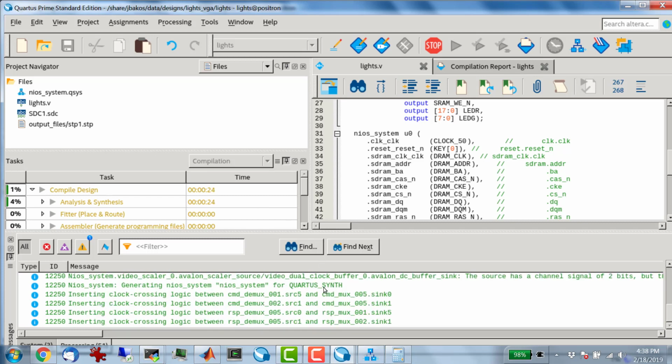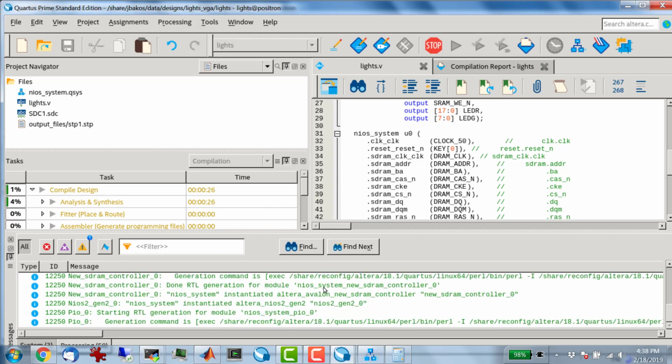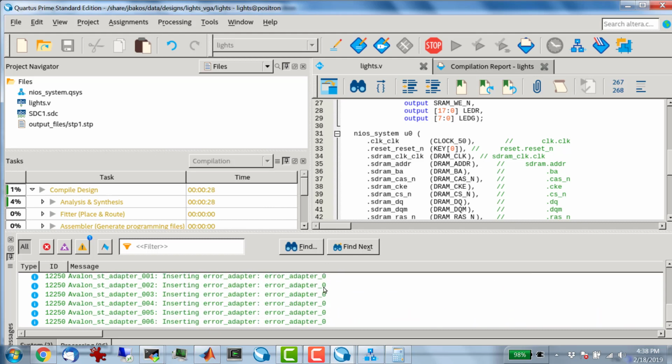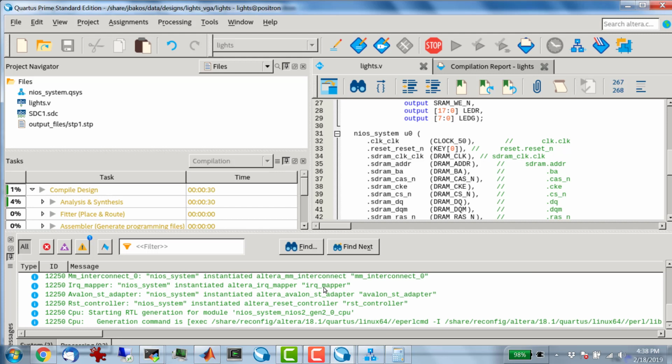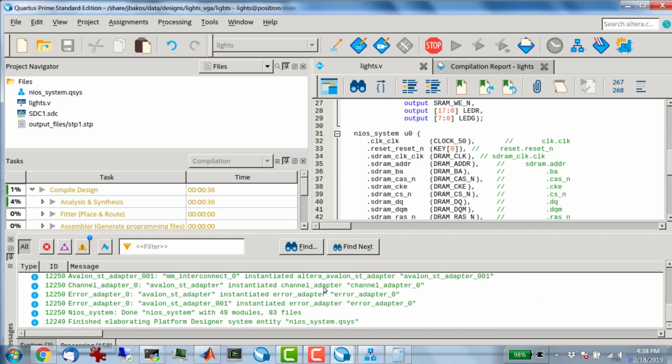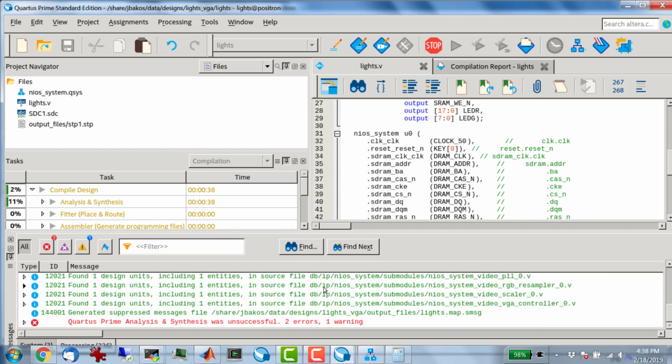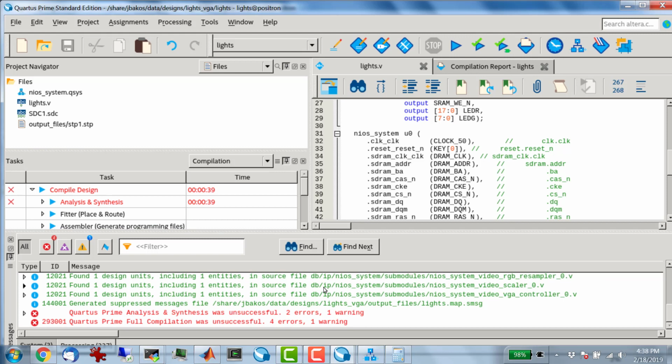So if this works, I should be able to watch what's going on on the DRAM interface, the SRAM interface, the VGA interface, and all the GPIO, the keys, the lights. I should be able to see that in a timing diagram, like a logic analyzer style timing diagram.